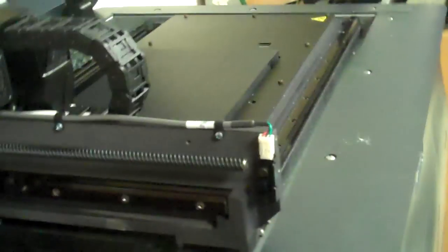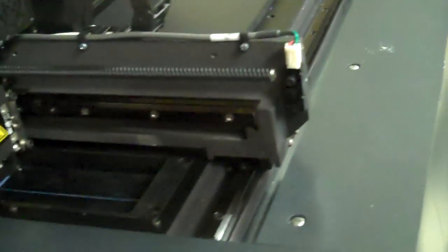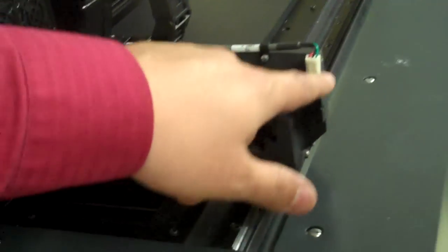Right here, this screw, this is the lead screw for it. How many ends does it have? How many starting points? 4. Yeah, it has 4 starting points. So that's a quad lead screw. So every time this turns, instead of going that far, it's going 4 thread lengths' worth.